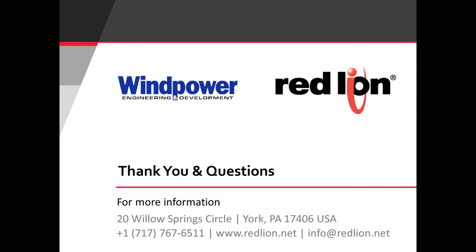Okay, maybe you answered some of this. Another listener asks, what tools are available to troubleshoot cabling and other issues remotely? Todd, do you want to take that one? Yeah, that goes right into what Diane's been talking about with the OPC server and NView and the ability to pull up things like frame check sequence errors or alignment errors. Alignment errors are typically related to fiber optic misalignment. We see a lot of fiber cables that could be poorly terminated.